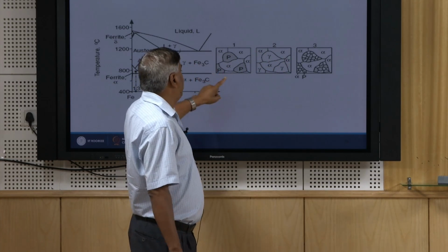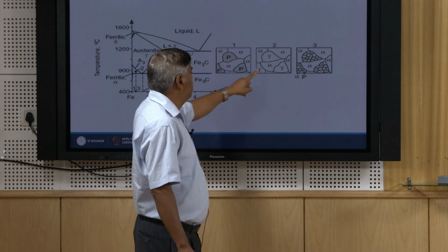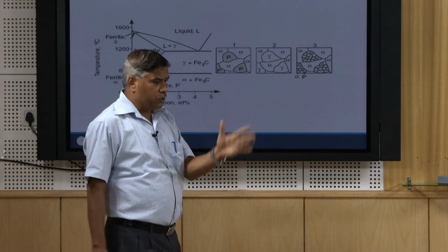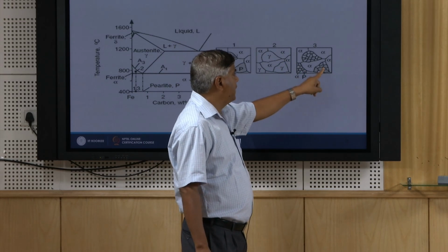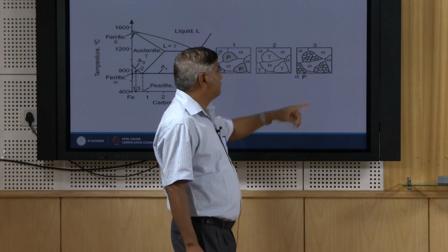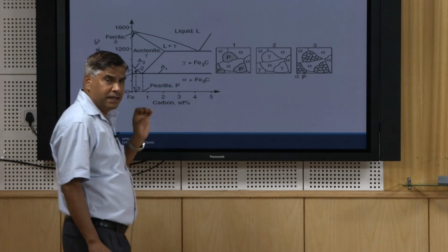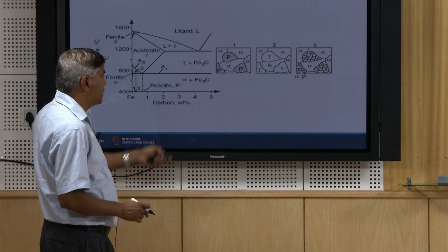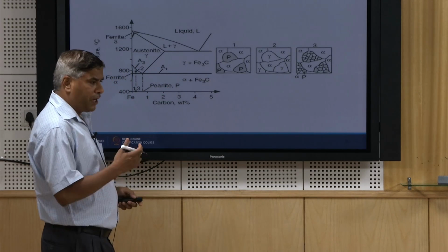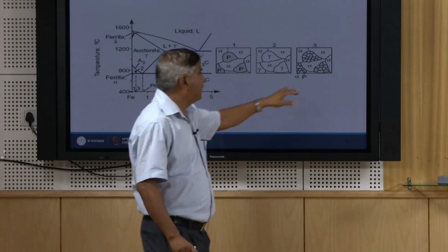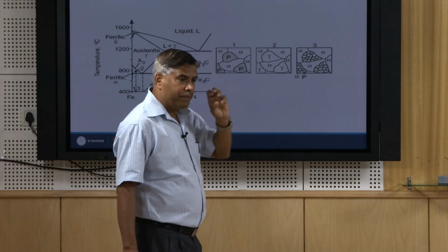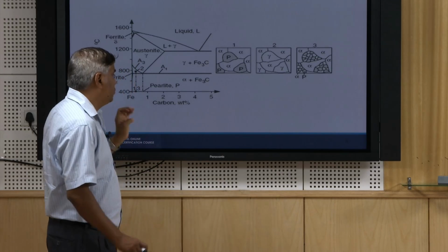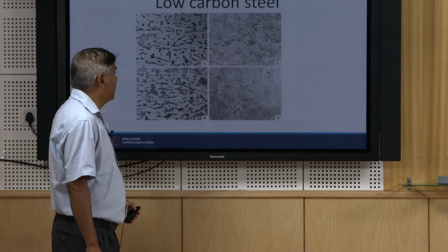So all pearlite grains will transform into austenite, and subsequent rapid cooling in the case of welding results in fine pearlite, while the ferrite grains remain as they are. So this results in the partially refined zone, because only the pearlite grains are refined due to the heating in the intercritical zone.